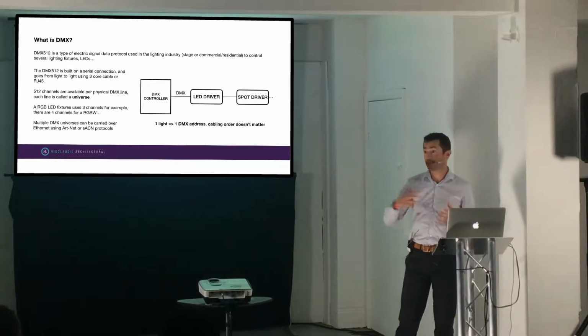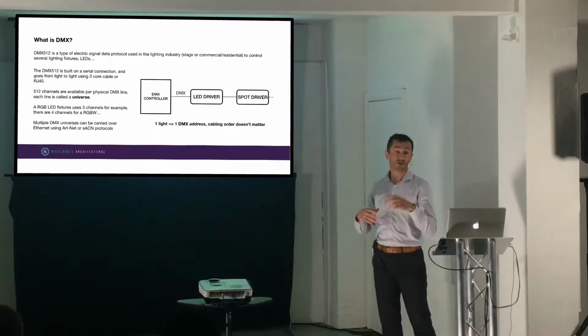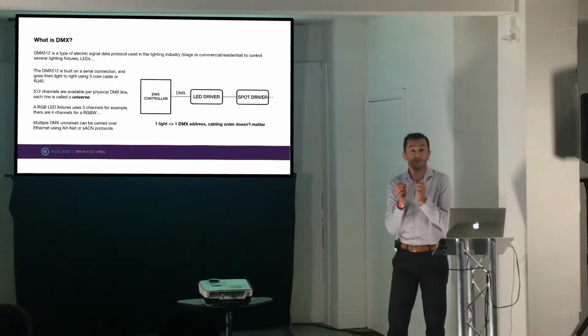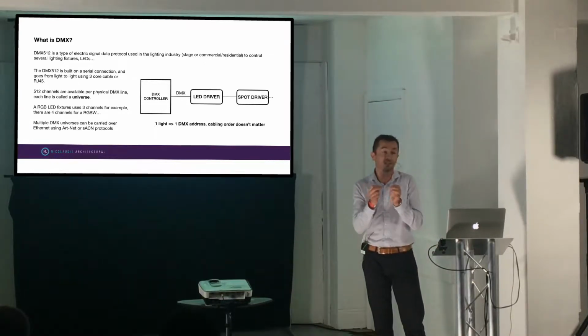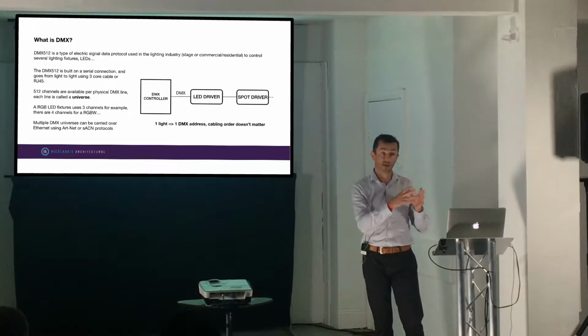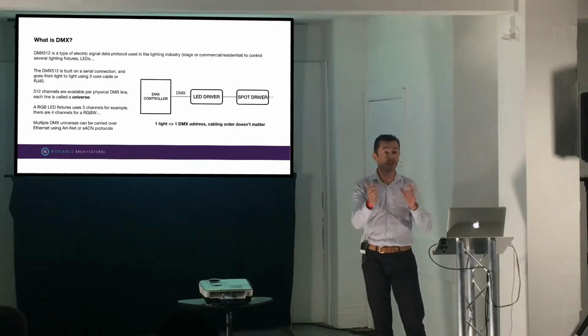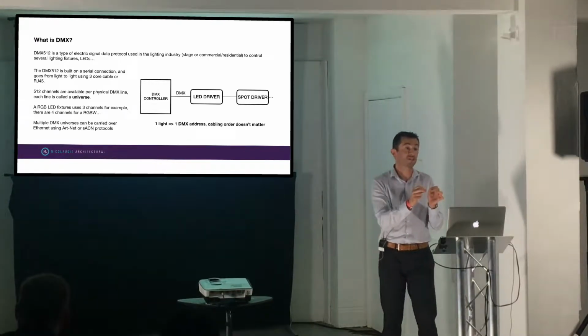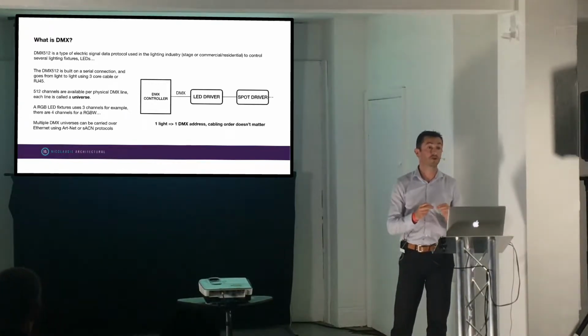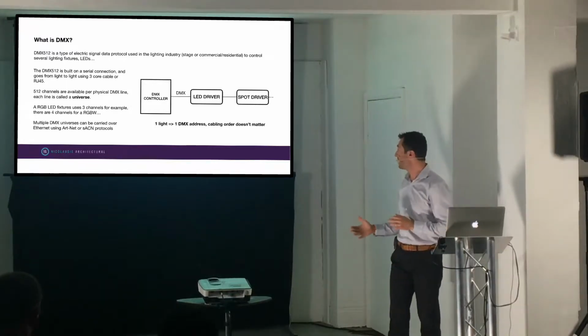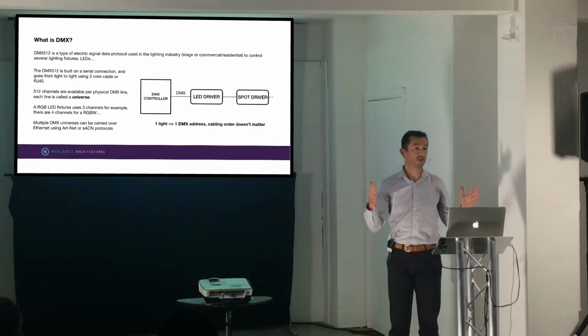This is built on a serial connection, and it uses 3 wires. This is the main thing that is important for this technology: you have to make sure it is correctly wired. That's the only problem compared to DALI. With DALI, there is no plus, no minus, no ground. Here, to start with, the most important thing is to use correct wires. When you're done with that, everything can be controlled.